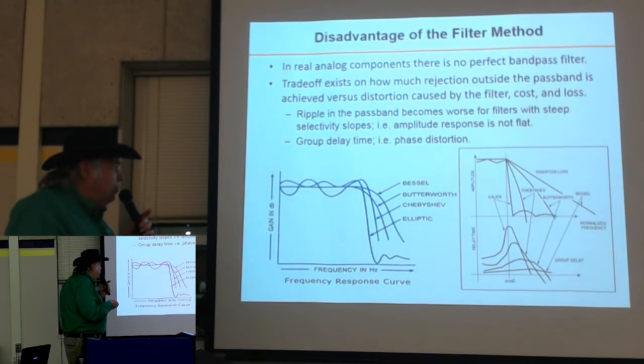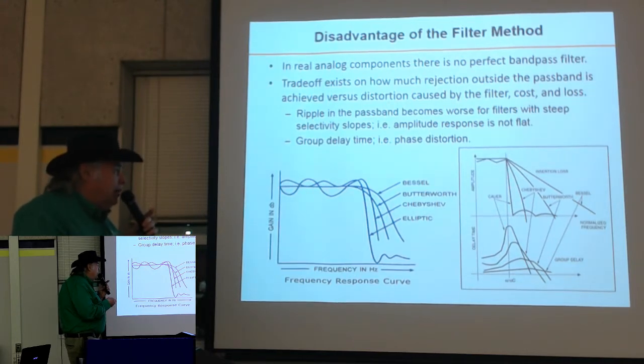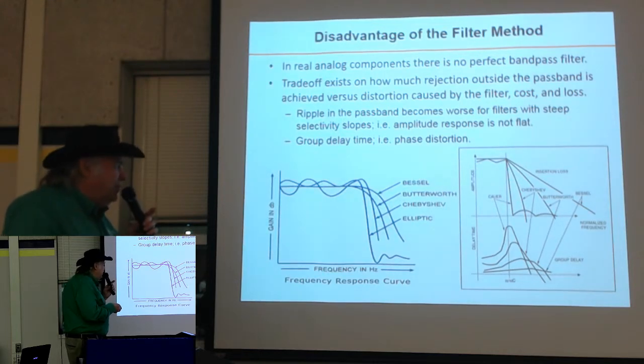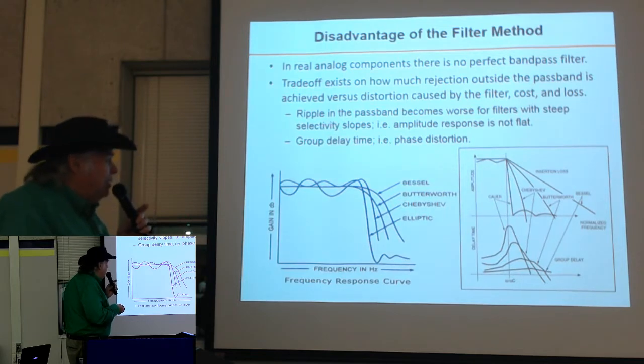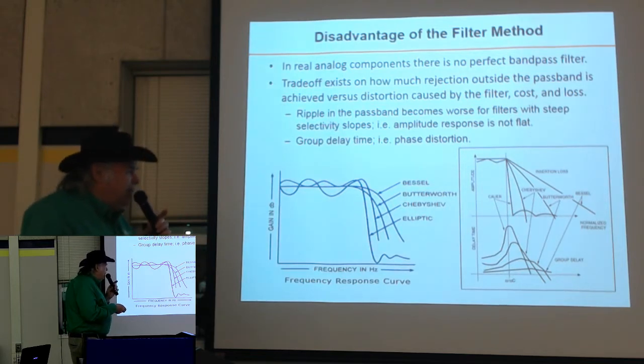Chebyshev filters are quite commonly used, and I think a lot of our filters are Chebyshev because of their roll-off characteristics. They do have some ripple, but you can control that, and you can design a 0.1 dB or a 0.5 dB Chebyshev. So by design you can limit the amount of ripple in the passband, and then of course, the less ripple, the less your falloff. So the filter response is not as steep, but again, you still end up with a lot of phase distortion.